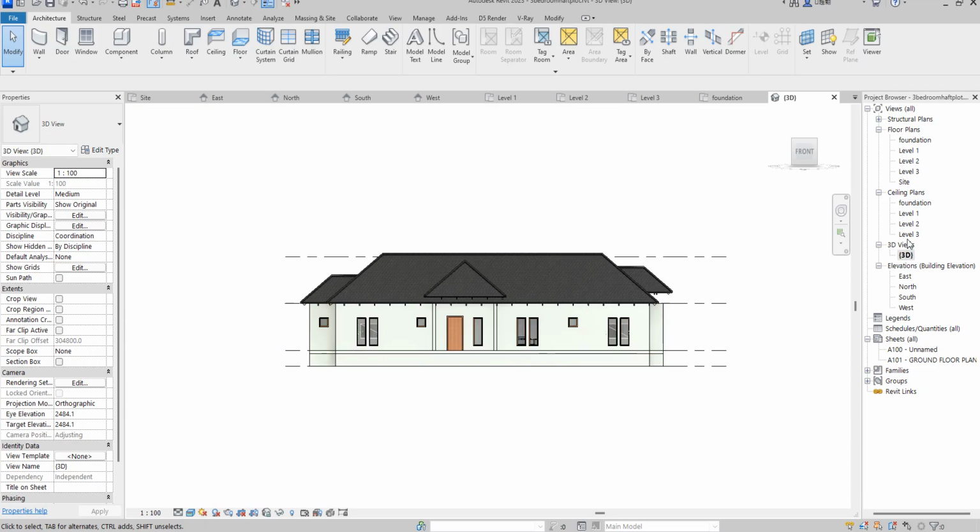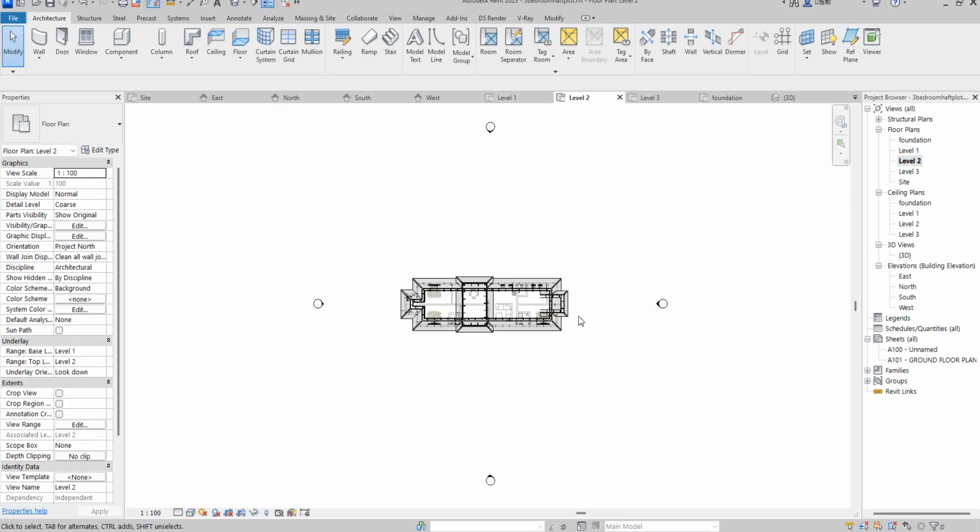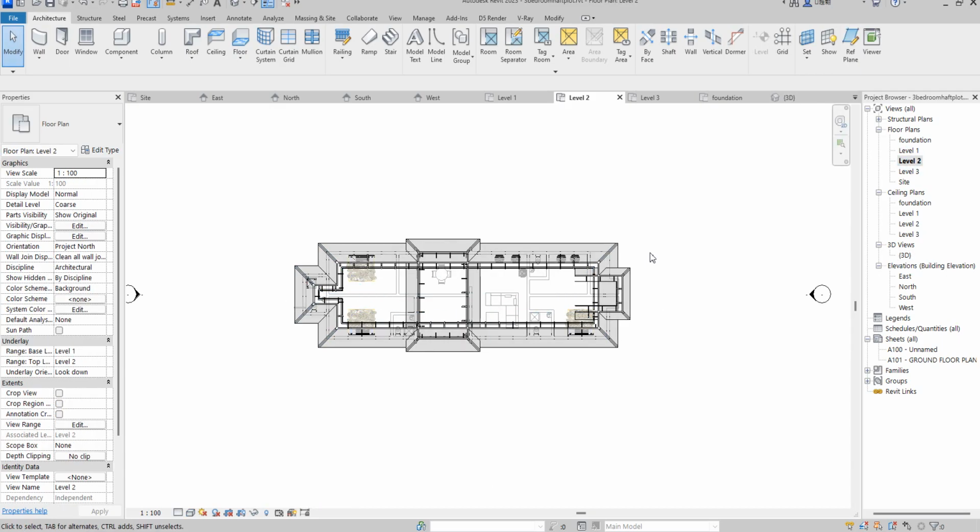Now what do you need now? You need to create a fascia concrete for that one. When you want to create fascia concrete, it's a simple thing to do, but you go to level 2 to do that, because that is where this concrete is. So all you need to do is get the perimeter of the longer one, then you do the design, then you copy it for those other subsequent roofs that you have placed on each other.